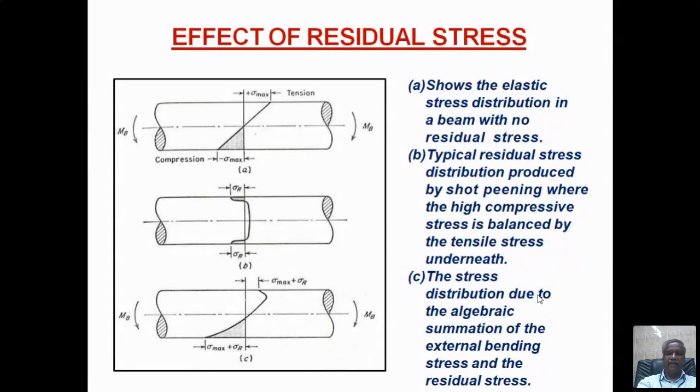If you combine the first and second, the sum of these two, the tensile stress goes down. It is not exactly on the surface because of the peening operation. The magnitude of the stress is reduced on the surface, and the peak moves inside, maybe 1 mm below the surface. By that, you can improve the fatigue life, because the crack normally initiates from the top surface, but now the maximum tensile stress field is just pushed inside the material. So the crack has to initiate from there, and that will take more time than the first case. That is the effect of residual stress here.